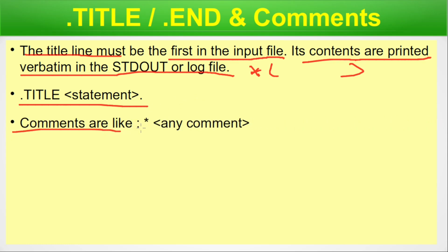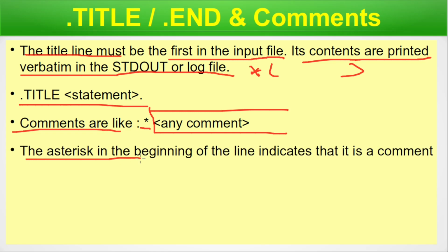Comments are like the star, and anything after the star is taken as a comment in the SPICE deck. The asterisk in the beginning of the line indicates that it is a comment. That means if you have to comment out any particular, say, analysis or component, you have to just put a star in front of the entire line, and that will be commented and that will not be considered in the SPICE simulation.